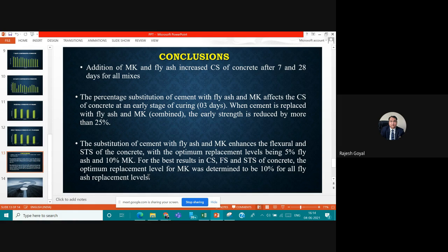Yes. Actually, based on our literature review, the previous researches where researchers have not used the blend of materials, like where researchers used fly ash or where researchers used metakaolin, in many places we found that M20 to M30 grade of concrete was used for their testing. But this is not a hard and fast rule, because when we are doing this kind of research we can focus on M20 also, M25 also. But we wanted to go for the material mix design also. So for M30 we have to go for mix design. That's why we have chosen this one.